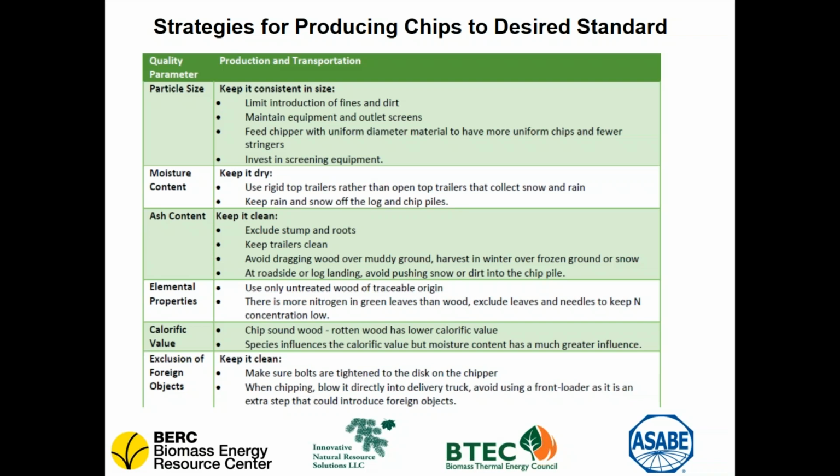Moisture is also a big deal. You would never want to burn green or wet logs in your own home fireplace, and wet fuel has low net energy, greatly increases emissions, and it has worse flowability and more probability of plugging in boiler feed systems than dry fuel. So please do whatever you can to keep your chip fuels dry.